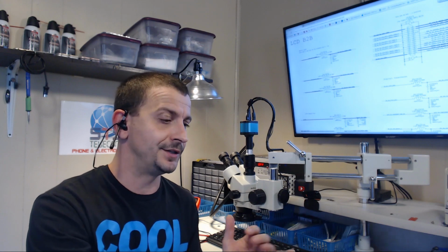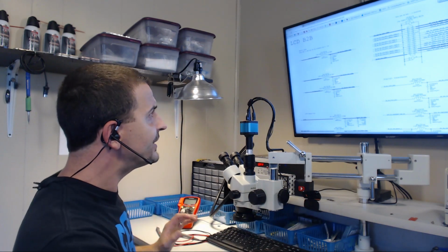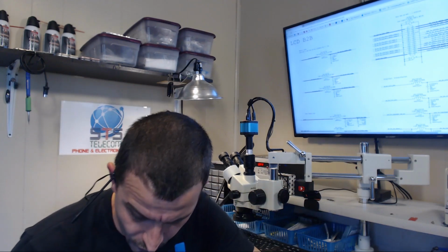I'm looking at the specs in the schematic and putting them in on DigiKey to narrow it down and find it. Now, the difference on the backlight coil, though, is that I didn't know what package size to go with. One of my viewers might be able to straighten me out, but I didn't know what package size to go with. So I dialed in my current saturation, I dialed in my maximum limits. I put in what our inductance is in microhenries. I put in our maximum current.